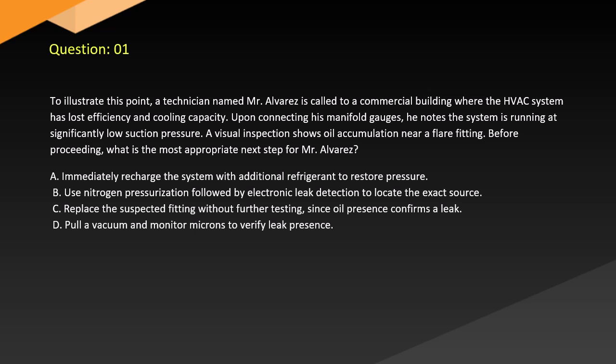Before proceeding, what is the most appropriate next step for Mr. Alvarez? A. Immediately recharge the system with additional refrigerant to restore pressure. B. Use nitrogen pressurization followed by electronic leak detection to locate the exact source. C. Replace the suspected fitting without further testing since oil presence confirms a leak. D. Pull a vacuum and monitor microns to verify leak presence.